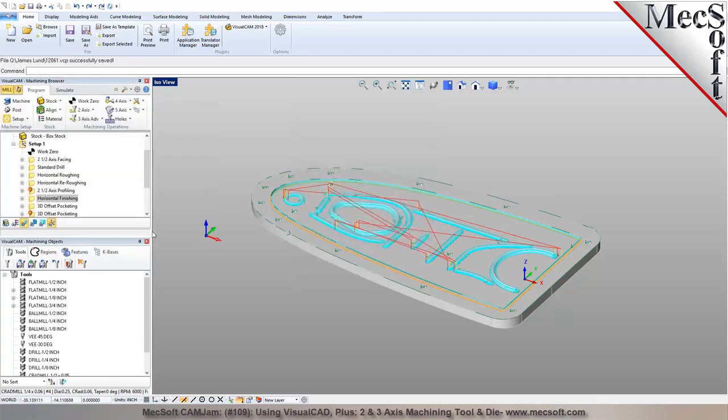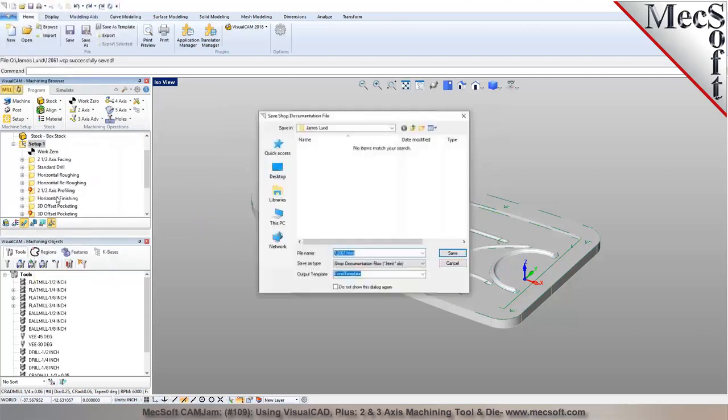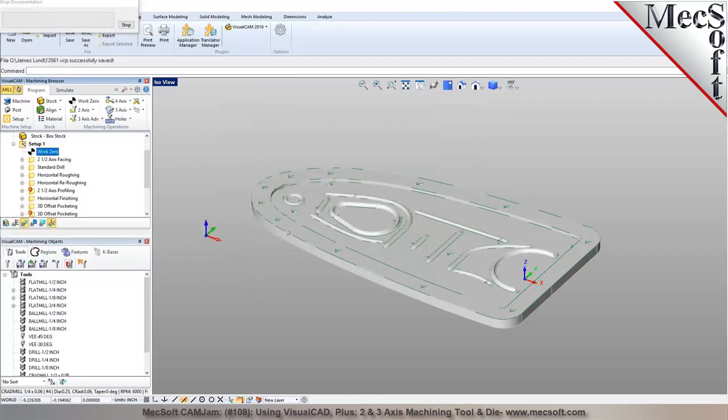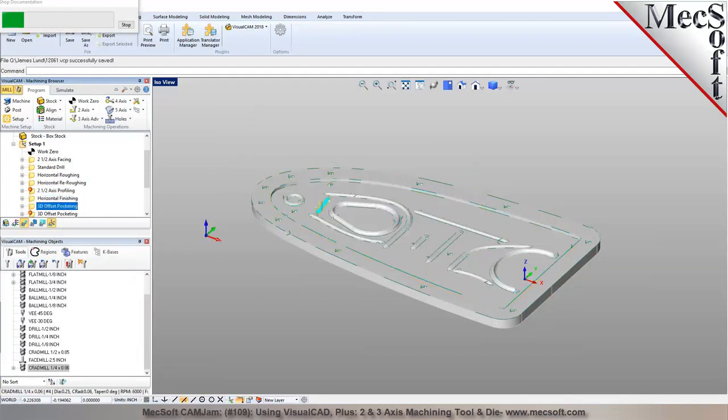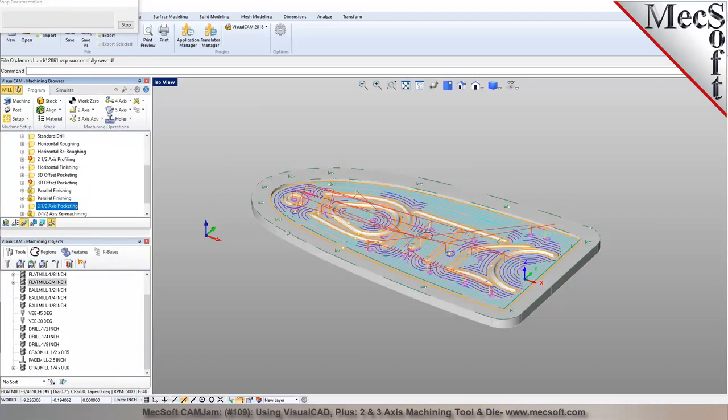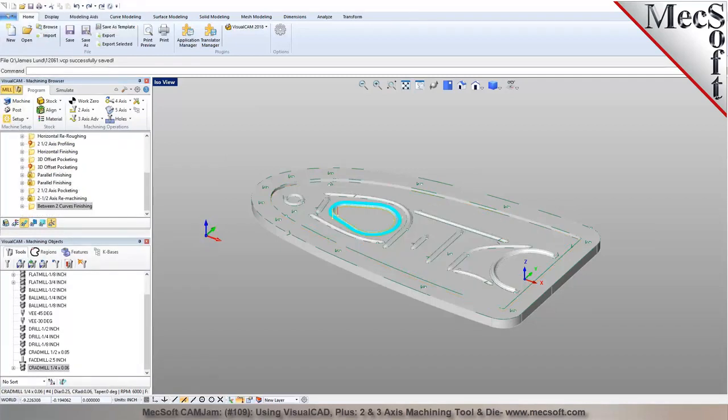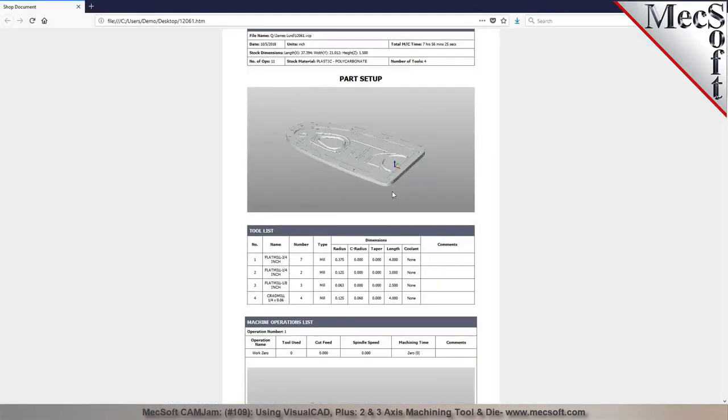Okay. And you had a question about shop documentation. So right click, shop documentation. We have 4 different template types. We have an Excel template as well, and additional template types. So you can pick one of these templates, and the templates can be customized. They're using standard HTML tags. So if you're familiar with XML programming, you'd be able to modify the cell spacing or width, or reorder some of the information in there. So there's some control available in customizing your templates.